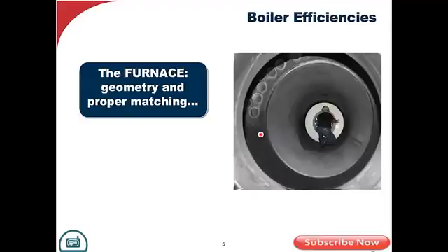Tremendous delta T. And as a result, the heat transfer is very, very extreme, and we want to take advantage of that. And that's one of the things that boiler designers today are doing, is trying to take more and more control and more advantage of radiant heat transfer in the furnace. But all in all, when everything is said and done, that furnace, its geometry, its length, its diameter, its configuration, its volume will determine the time.